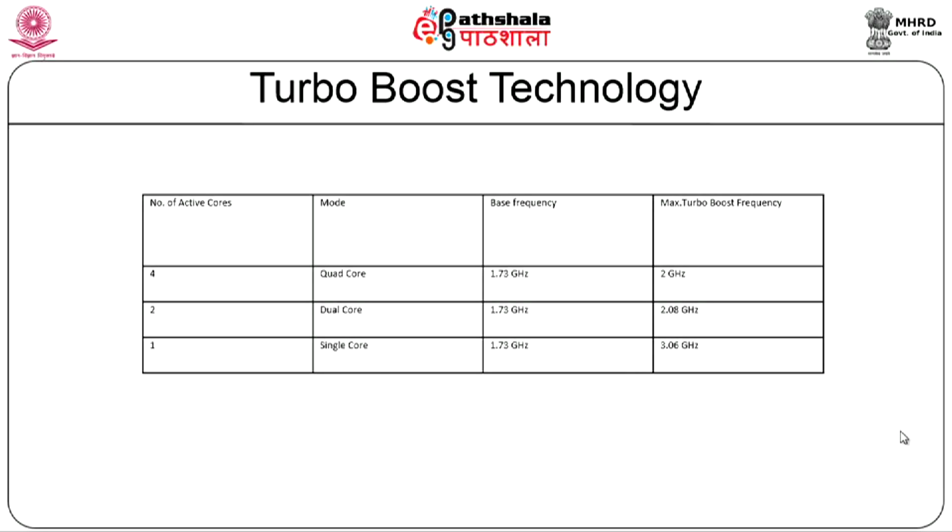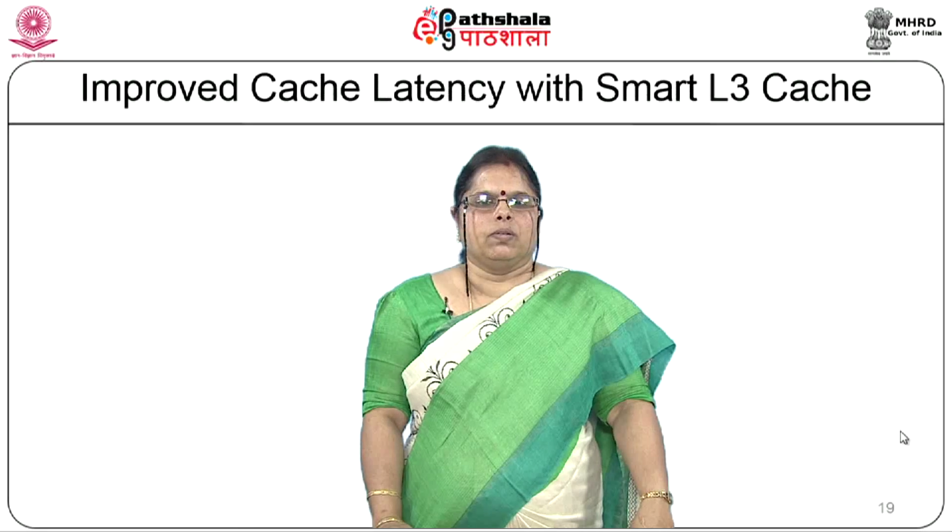So, that is the turbo boost technology, and all the time when you are boosting the frequency of a particular core, you always make sure that your thermal requirements are satisfied, your power requirements are satisfied and the current requirements are satisfied. If it goes beyond the threshold, then you bring down the frequency.